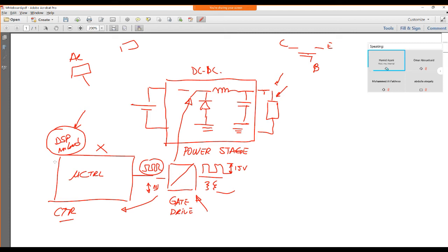Just designing one converter, let's say a buck or boost converter, one time, you'll be ready to design the other ones by yourself in terms of physical design. So now let's continue. I did all this just to explain the switching frequency, how we can select it. Switching frequency, you can select it. It has a big range. You can select it as you like. You can increase it. There is no limit, theoretically.